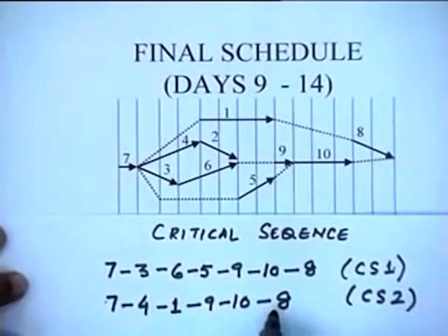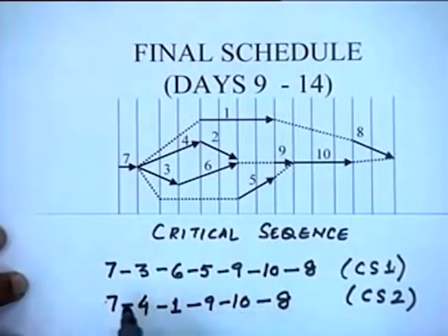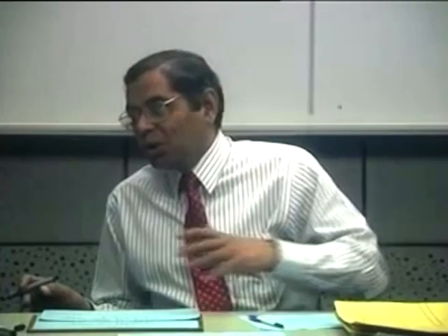The sum of the durations of all these activities is 14, but mind you, these activities are not strictly related by the precedence that is found in a conventional critical path, but the sum of the durations of these activities does lead to the total duration of 14, and it is not the critical path.